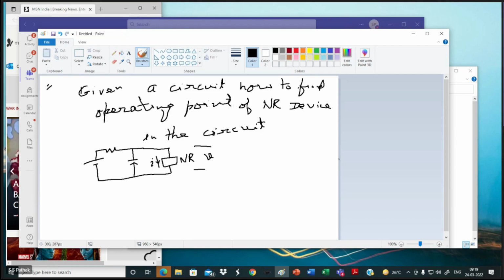If the capacitor is there, it will be charging exponentially like that. I can make an R and C combination such that it is charging with linear characteristic. That means charge is going as linear. By making R very large, I can make it linear, because I have to make R and C as large as possible.